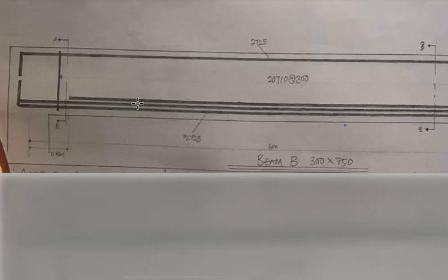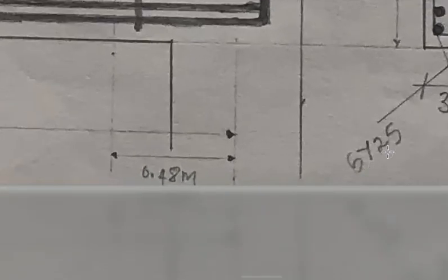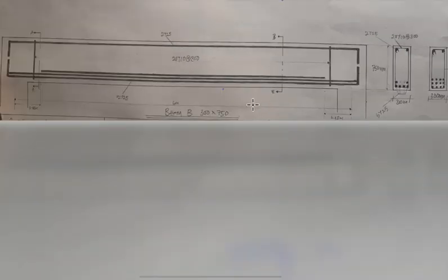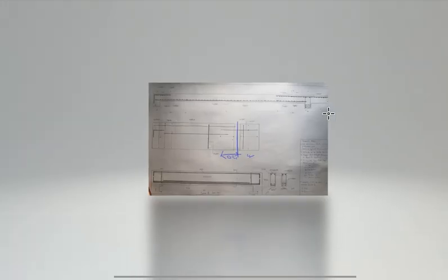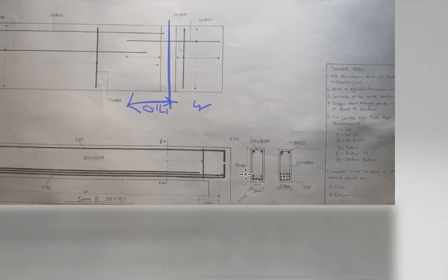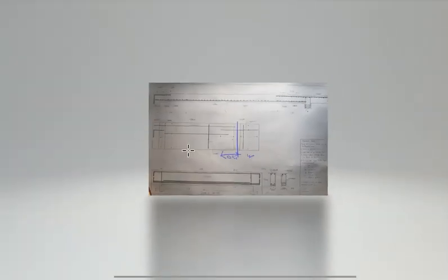So as I said earlier, you would cut the section just by the supports, and you cut another section at the center to show your full area. So you have 6 bars at the supports. So now you would be advised to go back to your textbook and read on curtailments. That would give you a lot more insights on how curtailment is done, or even understand it better than me.